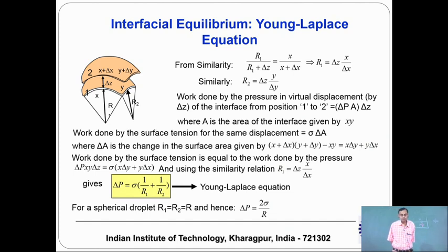surface tension. So, first is the Young-Laplace equation. Look into this figure. Here there is a membrane which is at configuration 1. By virtue of a pressure difference across this membrane it attains a configuration 2, where the dimension of one side, x, has become x plus delta x, and the lateral side, which had y dimension, has become y plus delta y.